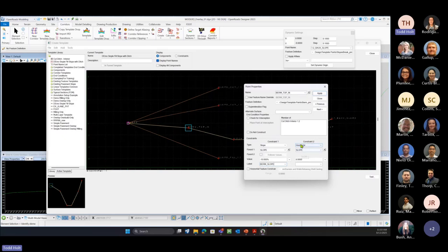Likewise, if we wanted a berm width for the horizontal, it's not always going to be 8 foot, or maybe it's 6, or maybe it's going to transition. This could be a parametric label that we put in for berm width. So that's going to make it this dynamic that it's not always going to be 8 foot. We can have that go from 8 foot to 10 foot by adding these parametric constraints in with using labels.